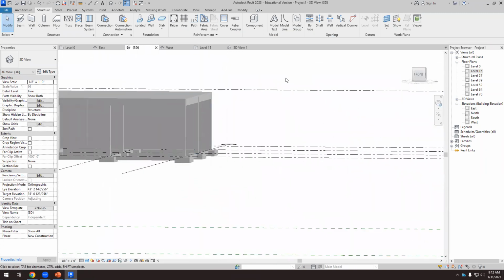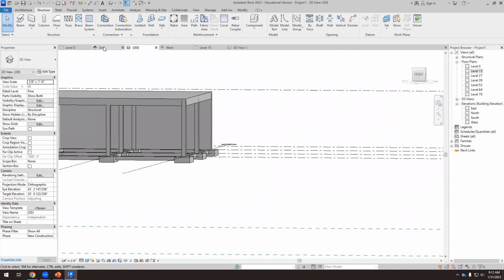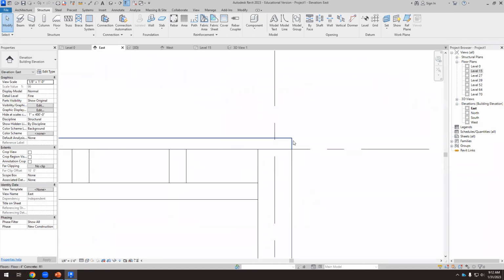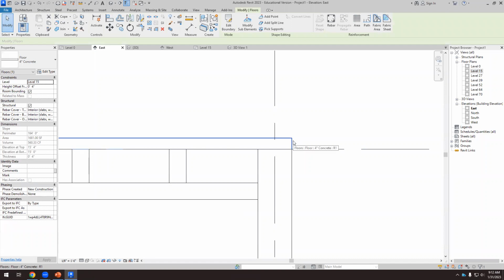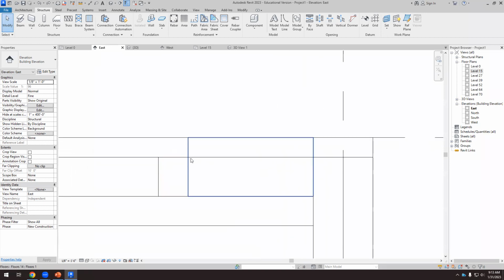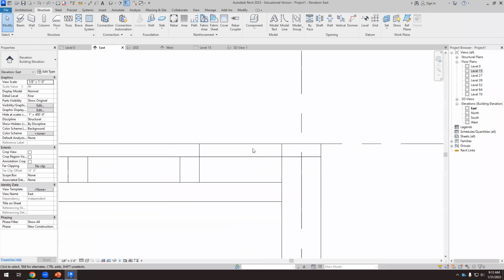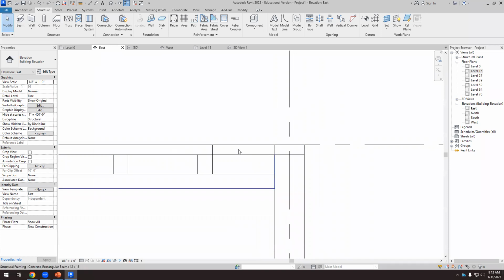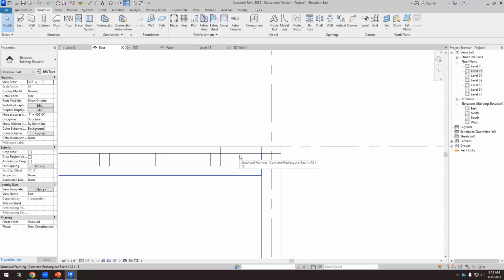Or, well, I don't know. Yeah, I have moved that floor 4 inches up, but it could be embedded, it depends on the height we want here. Anyway, this doesn't have to be more than 4 inches. It doesn't have to be a 1 foot floor because we have these joists.